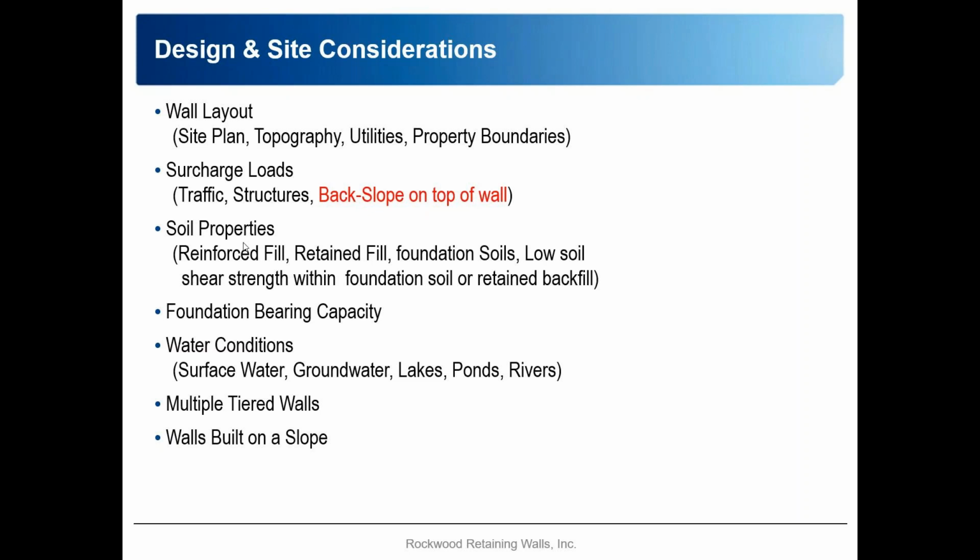Or maybe it's less obvious. It's along the side of a garage where the homeowner wants to park their RV. Well, that RV being backed in and parked along the side of a garage, if the retaining wall is 3 or 4 feet away, that would certainly be a surcharge load.